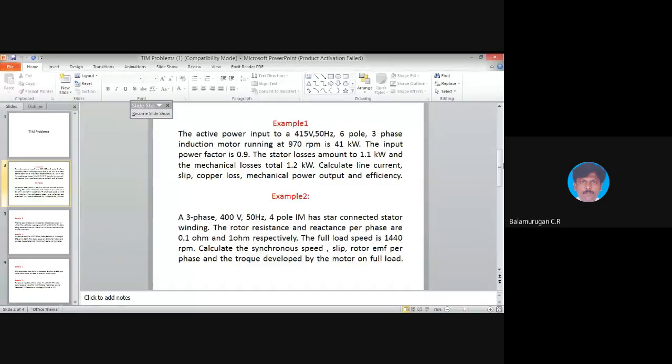Okay, within that range. And what will be the value of K generally? It will generally vary from 0 to 3 like that. Okay, and I am choosing 1.75. So from this expression, E1 by E2 is equal to 1.75. From this you calculate the E2 value. So stator to rotor turns ratio is not given in the problem. We are assuming this value. And E1 by E2 is equal to 1.75. You tell the value for E2.